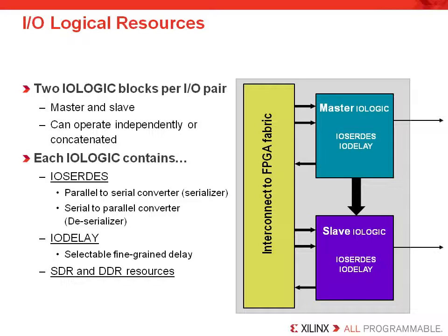The I/O SerDes capability includes input and output SerDes resources. There is an OSerDes parallel to serial converter for both OQ and TQ. It is arranged as a master and slave IOB pair to allow for differential inputs or larger single-ended bit widths. So not only can you complete 6-to-1 parallel and serial conversion, but when paired appropriately, you can do larger parallel and serial conversion. For this to be done, an appropriate master-slave pair must be found on the die. You cannot just pair any two IOBs and make them a master-slave pair. The SerDes functionality also has a user-selectable fine-grained programmable delay element for synchronization.